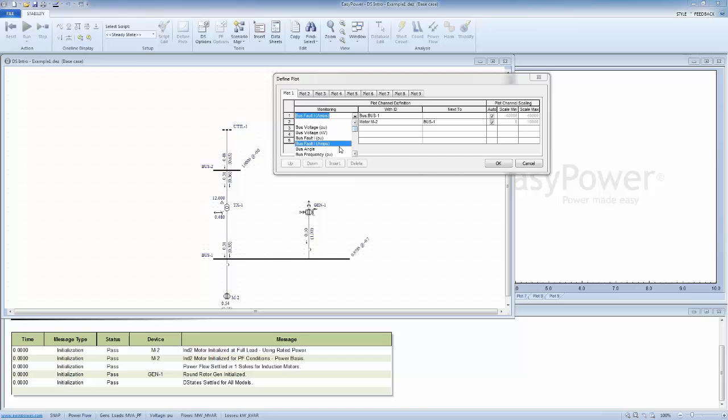And let's keep in mind, it's not a final result. It's a plot. So you can look at, let's say, the fault current, the bus angle, or the frequency. And for those of us who work with power systems and modeling, you know that when you run a load flow or a short circuit, you would never consider the frequency of a system.